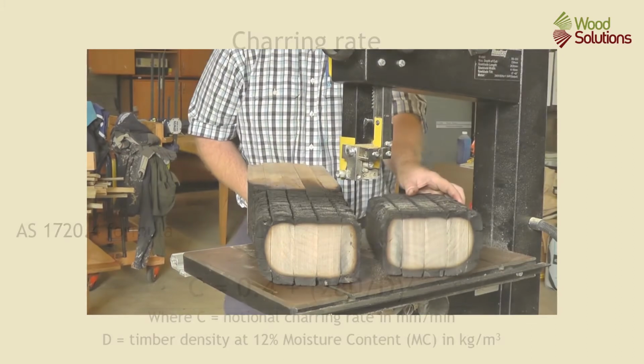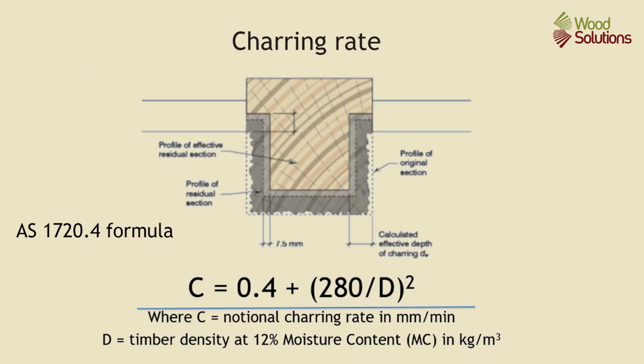The charring rate can be calculated, and Australian Standard 1720.4 provides a formula to do this. The formula is the charring rate, or C, in millimetres per minute, is equal to 0.4 plus 280 divided by D, that's the timber's density, squared. So the higher the timber's density, the lower the char rate.